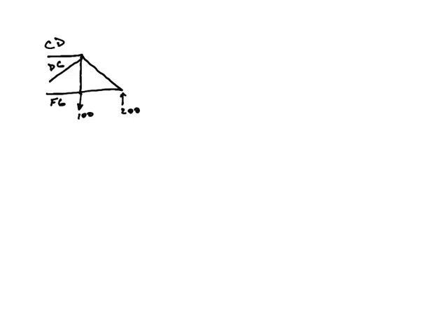All right, so there is the piece of the truss that I'm going to work with. And now I have to use my 3 equations to solve for these 3 unknowns, CD, DG, and FG. Now the next step is, before I start doing these equations, I need to choose a direction for the forces for each of these 3 unknown members.